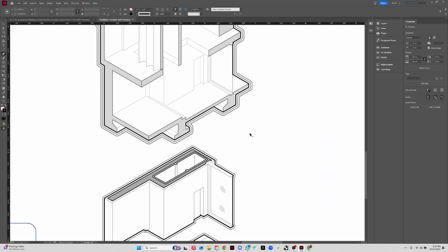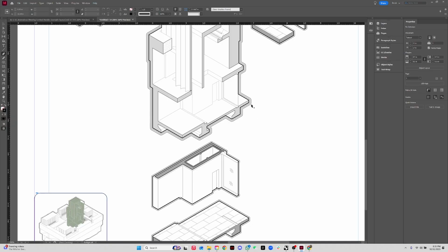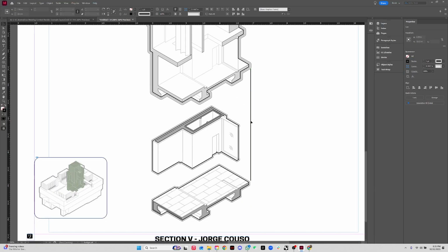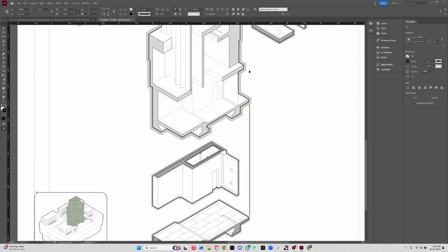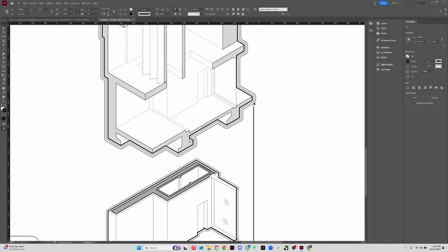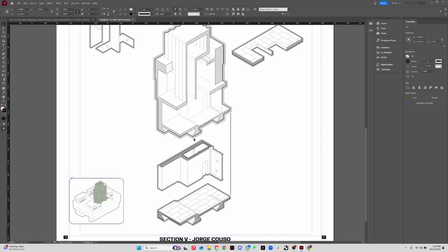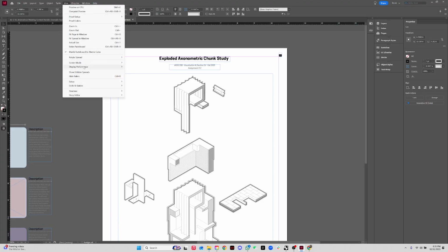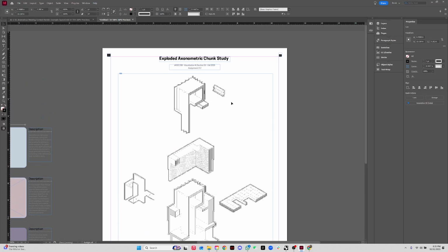and then I'm gonna start to think, where should I put these lines and where does it match better. So I'm gonna start just putting them in and trying to see how I organize it. For example, this one here, probably will do it here. Obviously I'm gonna change the line weight. Another thing, if your page is a little bit slow because the image is really high quality, you can always go to View, go to Display Performance, and put Typical Display. It just makes it faster.